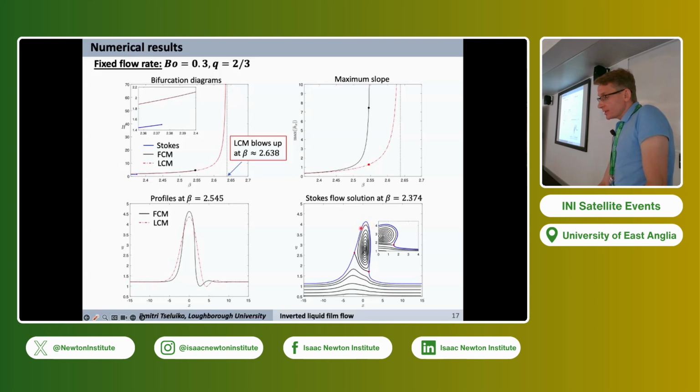angle, there is an eddy which is confined to the near tip region of the wave, but when the inclination angle approaches this critical value, the eddy inside the pulse increases, and the rightmost stagnation point moves downwards to the heel of the pulse. We computed the curvature at this point, and we found that it increases.